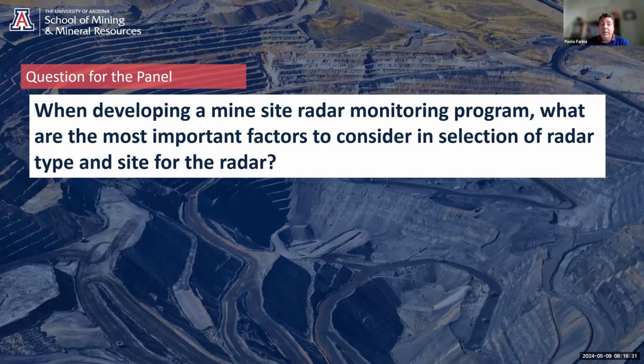Another important point is if you are dealing with very brittle failure mechanisms that develop in a very short term with minimal deformation. From my experience, it would be good to install a radar close to the bottom part of the pit, close to the slope, in order to get the best resolution and line of sight we can get, and also to be able to measure even minor movements that develop in 30 minutes, 1 hour.